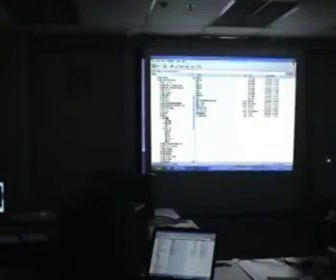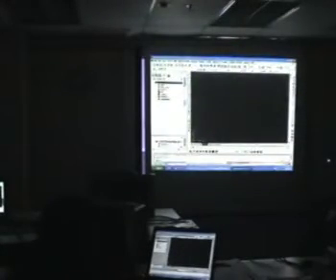Civil 3D is drawing based, so the only thing you need to do is just back up that drawing. And another major difference between Civil 3D and Land Desktop is that Civil 3D is very much object oriented. Land Desktop is just project based, right? But Civil 3D is object oriented, meaning if you move the horizontal alignment, the vertical profile is updated at the same time. So what I'll do is I'll just show you what it can do.